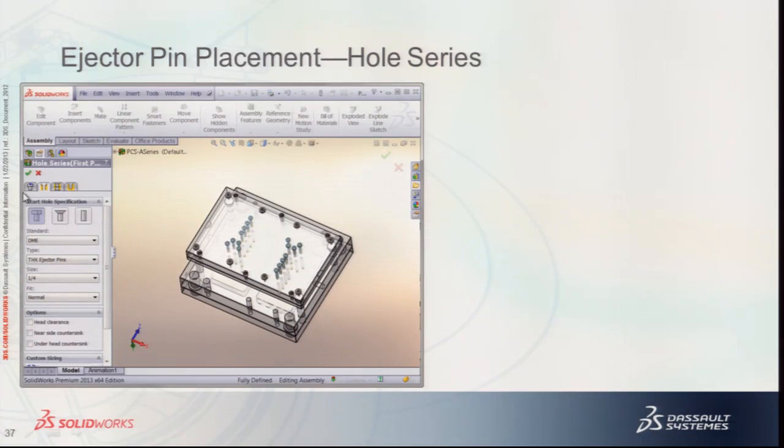So essentially what I did is I hit the hole series, and it's easiest to pre-select your plane and then hit hole series, because that results in a 2D sketch. And the way the hole series works, as opposed to the hole wizard in the individual SolidWorks part file, is different. They haven't quite updated it such that you don't have to pre-select. You have to pre-select a plane in the hole series, whereas with hole wizard, you can just hit hole wizard and then go off a 2D sketch. But this is different. So it's always best to pre-select your plane, and then you're brought to this property manager.